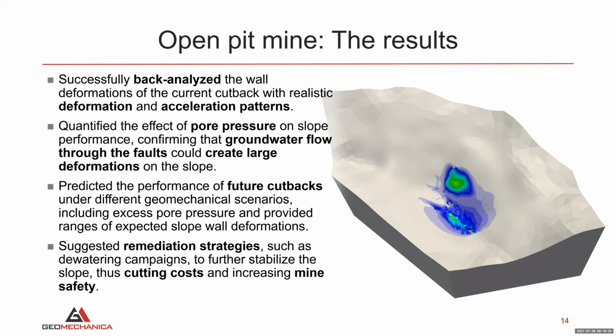We then predicted the performance of future cutbacks under different geomechanical scenarios, including excess pore pressure, and provided ranges of expected slope wall deformations. And finally, we suggested remediation strategies such as dewatering campaigns to further stabilize the slope, thus cutting costs and increasing mine safety.